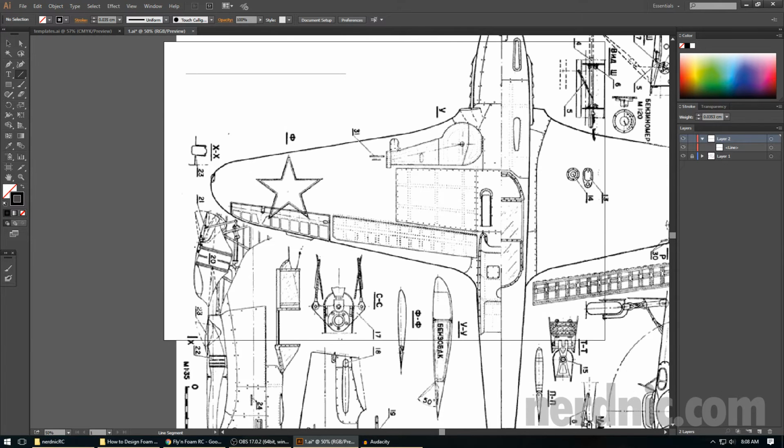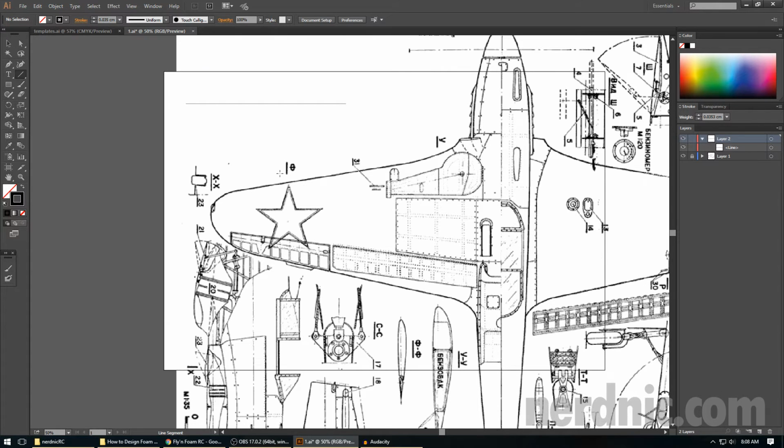So I'm going to go ahead and zoom in a little bit, and on this leading edge I'm going to draw a straight line starting at right about where the curve would be. And now I usually try, the best I can, depending on the wing shape, to line this up with where the aileron ends, if possible. If it doesn't, it's totally fine, it doesn't matter, but it just makes the inside bevel line a little easier later. But for this one, it's about right, so I'll start right about here. I'm going to click and hold with my left mouse, and I'm going to drag.